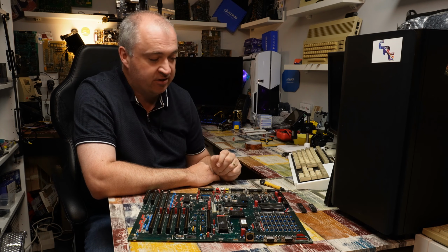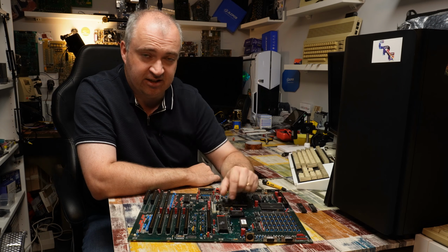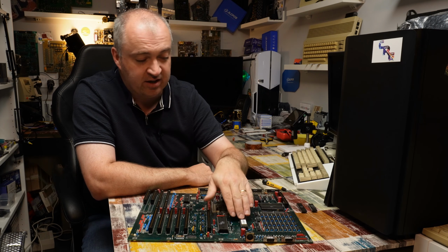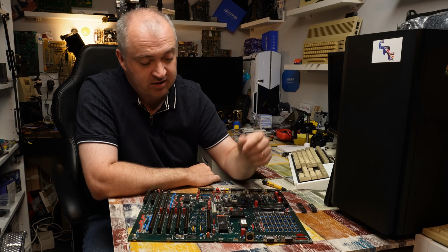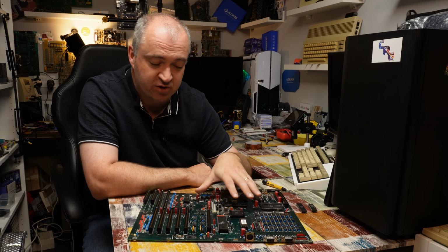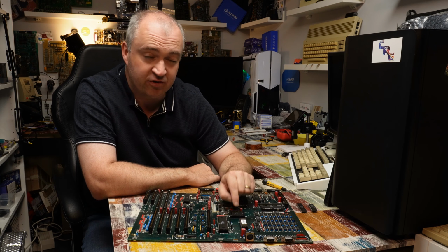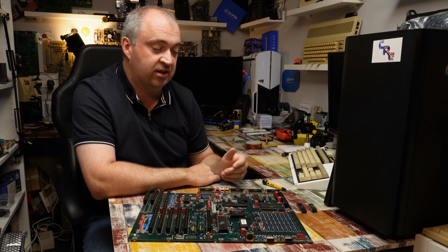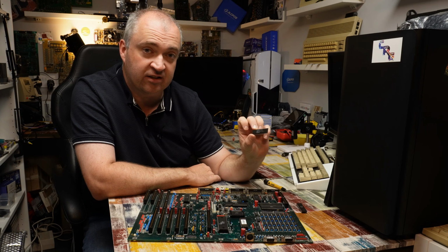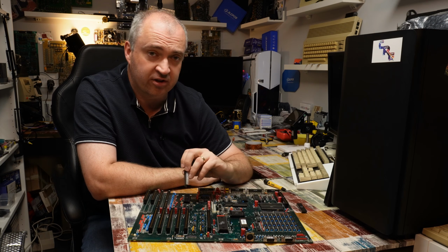And then the final things, well, they're just down to swapping out the chipset. As we said last time, this board originally would have shipped with an OCS chipset. So it had a Kickstart 1.3 in it. It would have had an 8371 Agnes, but the previous owner of this had already upgraded that to the ECS 8372A. The tech notes tell us to change the Kickstart to a version 2.04, just like this one, but I've got 3.1 in there. I'm just going to leave 3.1 in there.